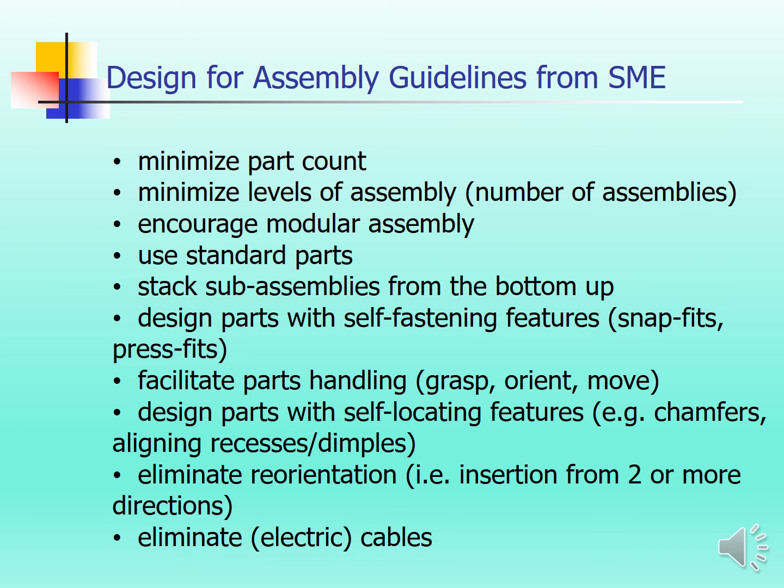Okay, here are guidelines to reduce assembly: minimize part count, minimize assembly levels, encourage modular assembly, and reduce non-standard parts and so on.